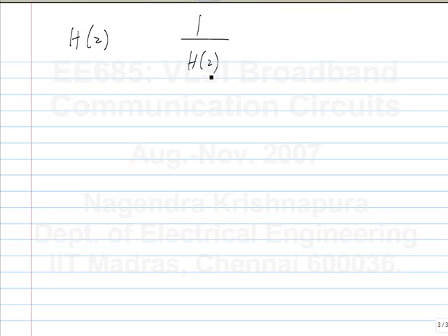Usually what happens is, there is a range of eye opening or range of bandwidth for which you can do blind equalization, that is blind adaptation. You have the equalizer, and without any help, with the actual random data, it adapts the right coefficients. Now, as the bandwidth further reduces, you may need to train the equalizer with some known data, because now it has a hard time adapting. But it is possible to equalize it. So there are two things, equalization and adaptation. Adaptation is the harder one if you have really bad data. Equalization, mathematically, certainly, if you have h of z, you can implement 1 over h of z.